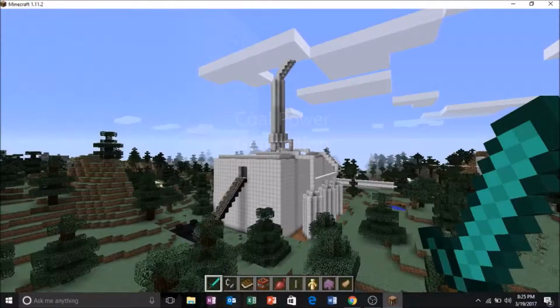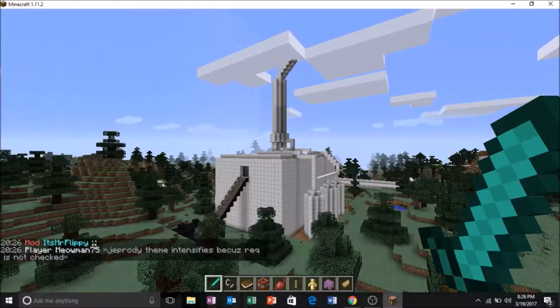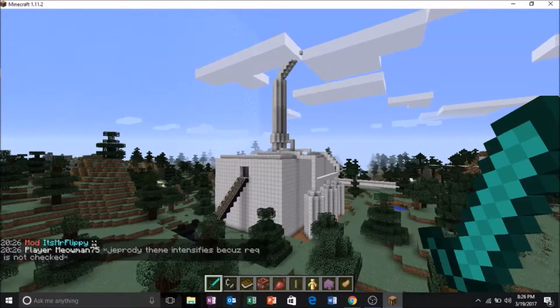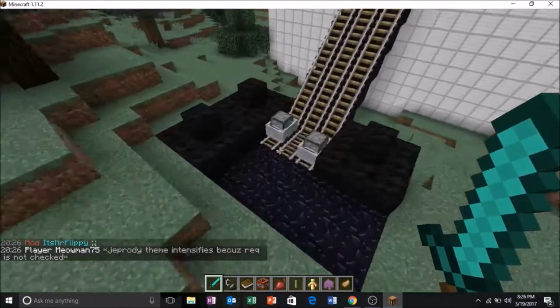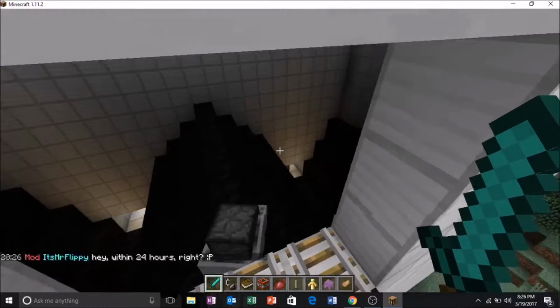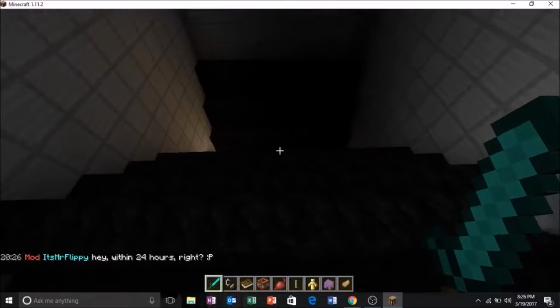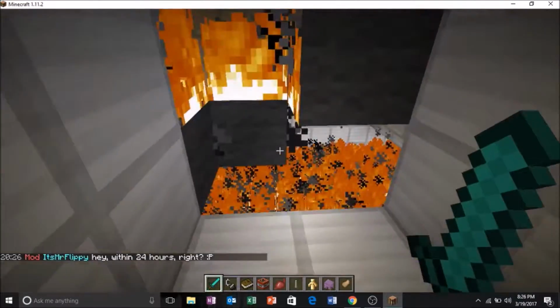This is a coal power plant. Coal power plants turn coal into energy by burning it to heat water, which turns a turbine. First, coal is transported up a conveyor belt into a pulverizer. In the pulverizer, the coal is crushed into a fine powder and is sent to a boiler.